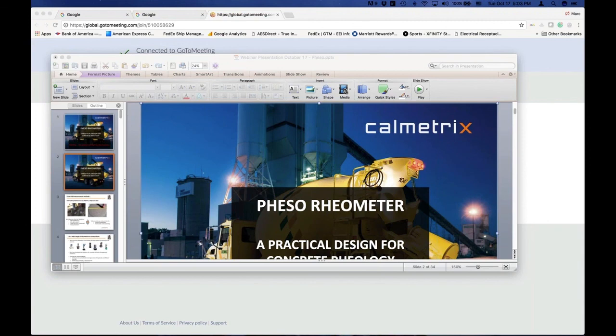Bruce, did you observe a significant difference between the traditional slump test and the rheometer results? No, actually no. Once you have correlated your slump results to what you would get in the Rheometer, the correlation is very good. So you get results that are very predictable. Looking at your rheology curve, you can predict the slump pretty nicely. But as I said earlier, the Rheometer shouldn't be used just as a slump meter. It would be a waste of resources, a waste of money. For slump, you still have the slump cone. It works very well. The Rheometer should be used for more than that.